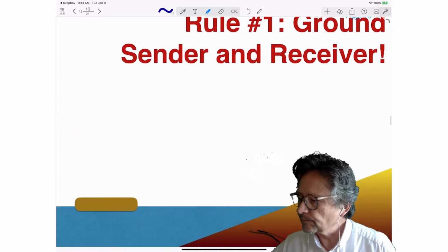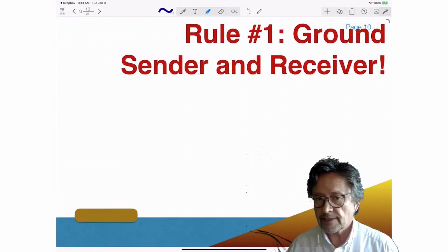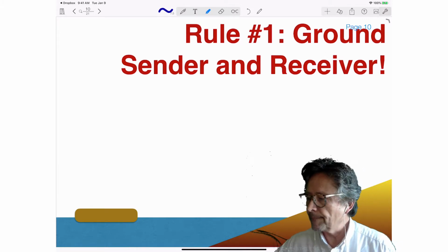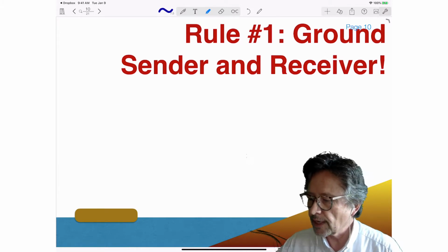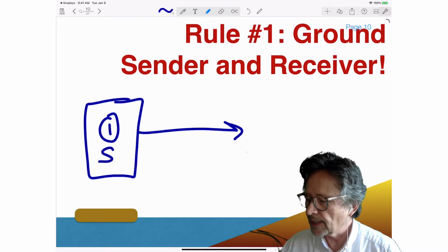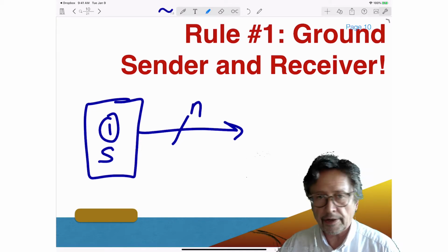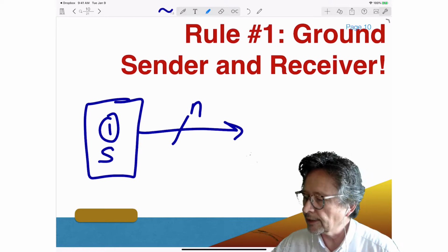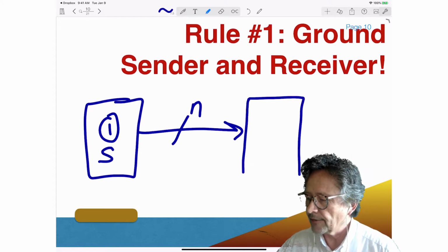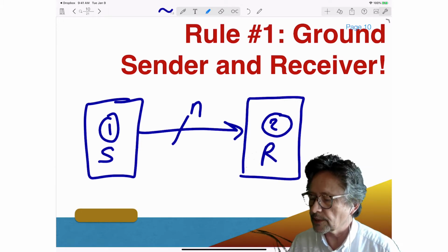All right. So the rule that I want to emphasize here is that whenever you connect 2 devices together, so you have device 1, so that's the sender, and it's sending information, so you have many wires. So that's typically a way of representing a collection of wire. We just saw 1 arrow, we put a slash through it, and we write the number of bits. I have n bits sent from device 1 to device 2. Device 2 is the receiver.